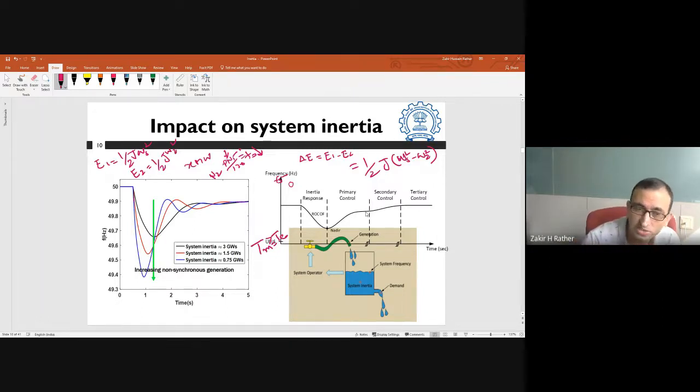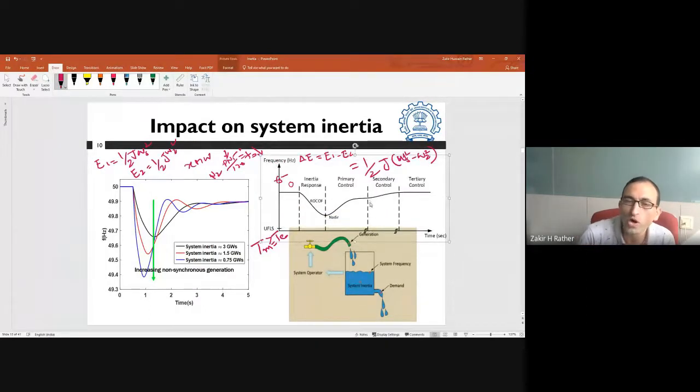This happens because of the natural laws of electricity and because of the magnetic locking between the rotor of the synchronous machine and the grid frequency. So it is this inertia, the rotational energy stored in the machine, that gets released instantly to the grid. This instant power support provided to the grid by the synchronous machine is known as inertia. And this is what precisely saves us from losing the integrity and stability of the grid at the start of the disturbance.